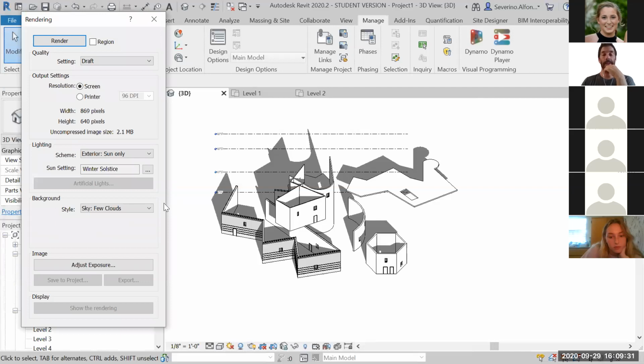Rendering settings in Revit are incredibly dummy, which is good sometimes to have dummy things and not so sophisticated. How does it work? You have settings. Setting is the quality, you know, you start maybe on medium, don't start with high or best, stay medium, do a rendering, feel comfortable, then jump to high.